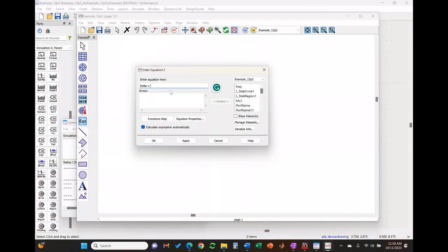And the notation itself is a bit intuitive. For example, if I want to find the magnitude, you just say abs. This is the same function we have in MATLAB. And then the equation in the slides is the absolute value, or the magnitude, of S11 times S22 minus S12 times S21. So now I'm going to recall that I want S11 times S22 minus S12 times S21.